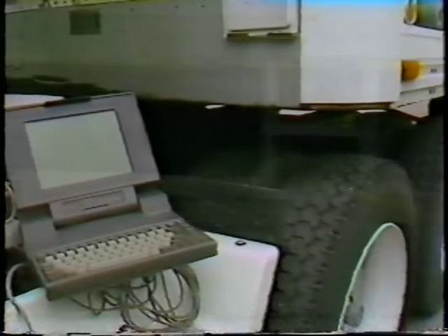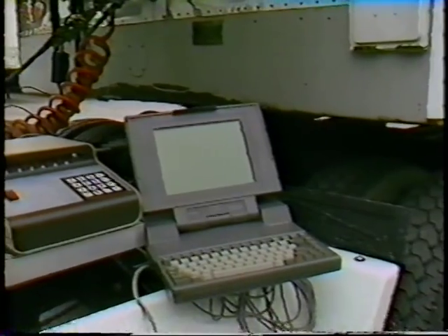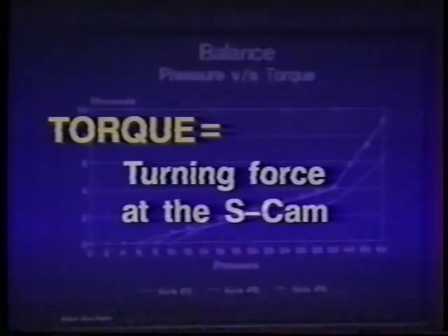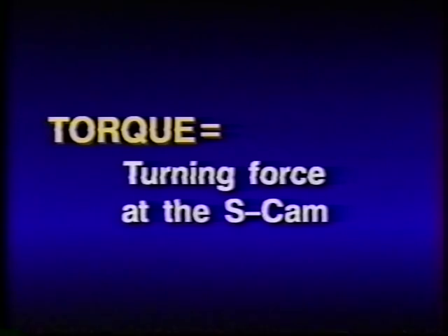balanced pneumatic performance for the entire rig. When problems occur, the best solution may be to take advantage of the highly accurate computerized pneumatic and torque analysis services offered by Ferodo America. Torque balance involves the turning force at the S-cam.